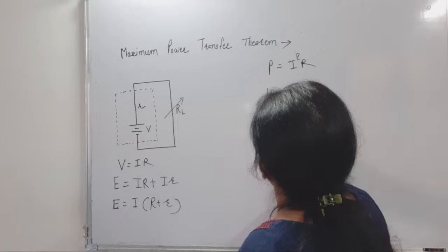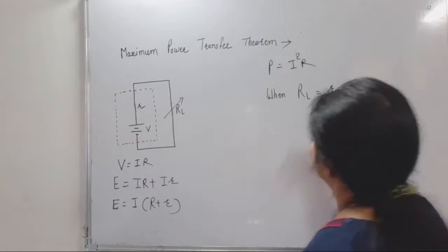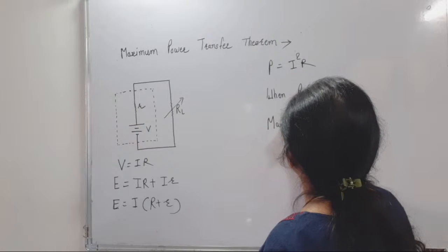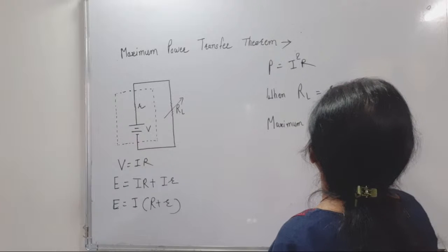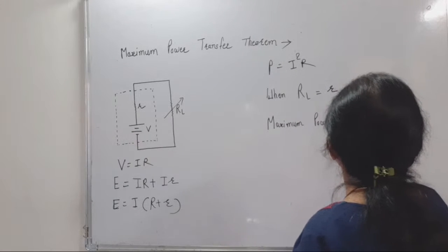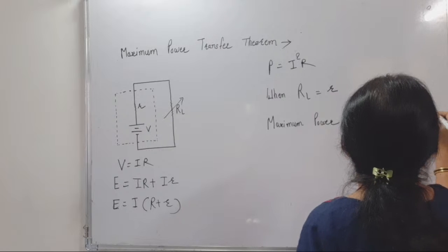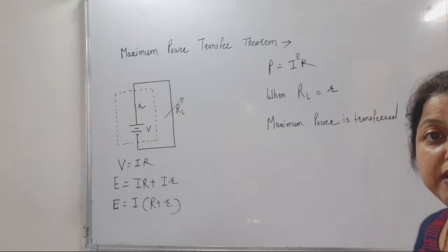So when that RL load resistance is exactly equal to internal resistance, maximum power is transferred to load. Okay. So that is the statement of maximum power transfer theorem.